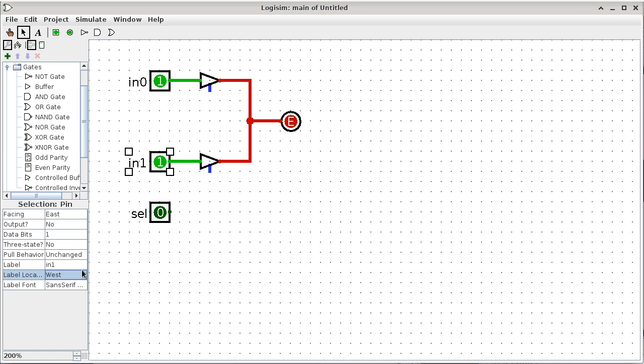This is basically what is happening inside a demultiplexer. Okay, so inside the demultiplexer, it's kind of the same kind of circuit, but not exactly the same. So I'm going to use the select pin here and connect it unnegated to 1. But I do not want to connect it unnegated to the other one, because otherwise both will turn on at the same time and both will turn off at the same time, which kind of defeats the whole purpose of the circuit. So what I would do instead is to negate it first before I feed it to the other one.